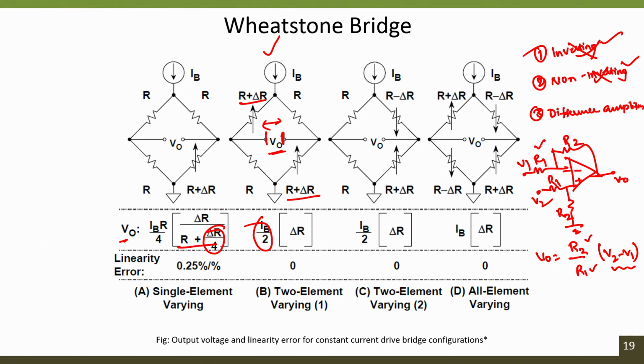But because of this R1 input resistance, the input impedance of the system entirely depends upon R1, and in this case, since the output from the previous stage is not directly connected to the input terminals of an operational amplifier, the chances of having loading are higher because of the input resistance value. Selection of input resistance is also very much important.